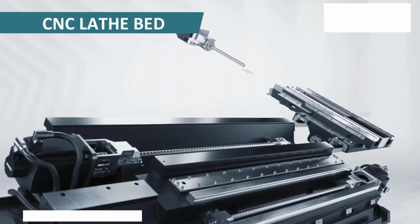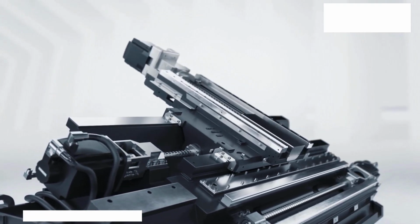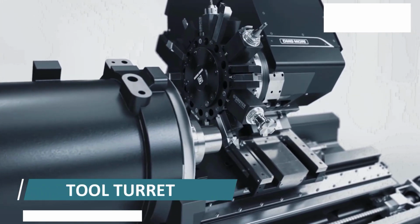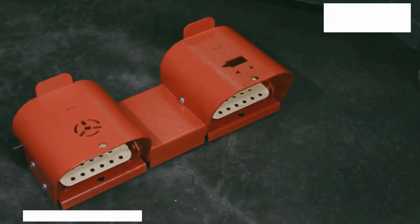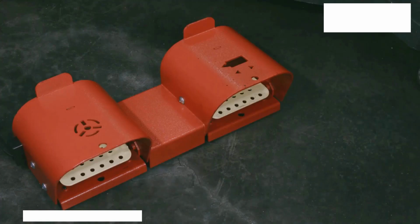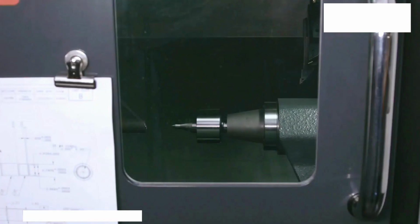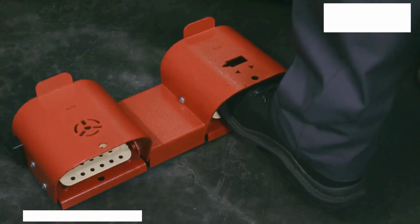CNC lathe bed. The tool turret travel over the CNC lathe bed, which is specially hardened, so any kind of machining can't affect them. Tool turret. The turret that holds the tool holders and indexes them as needed. Foot pedals. Foot pedals are used to actuate the chuck and tailstock quill. Through these pedals, CNC machinists open and close the chuck to grip the component, the same way tailstock quill is taken to forward position or reversed through these pedals.